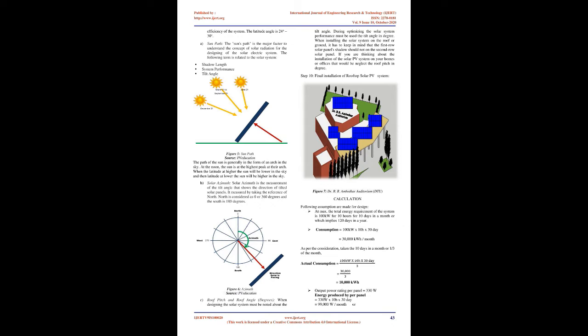Step 3. Navigation. When you are in 3D mode, you can use the scroll button of the mouse to rotate your drawing or image around. Using the track wheel you can zoom in and zoom out, and you can also do it by using orbit. The pan tool is used for moving the image or design.